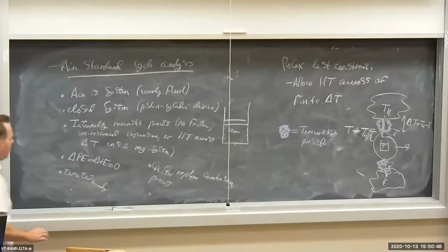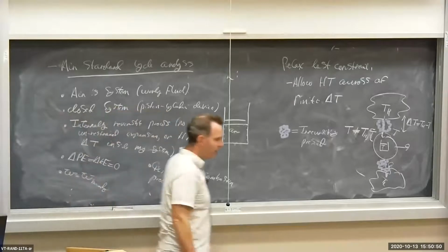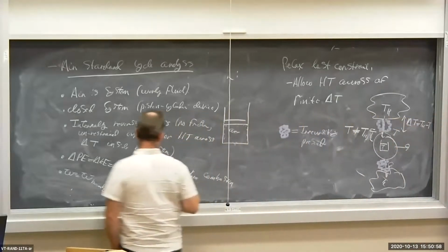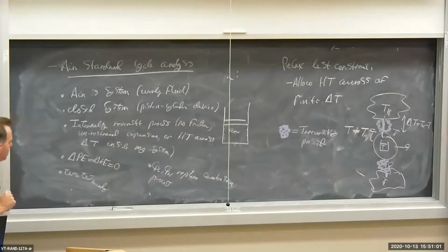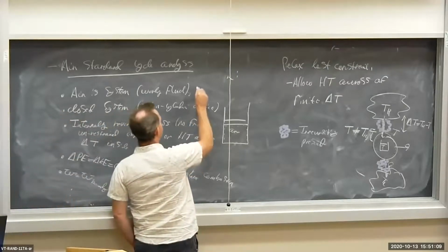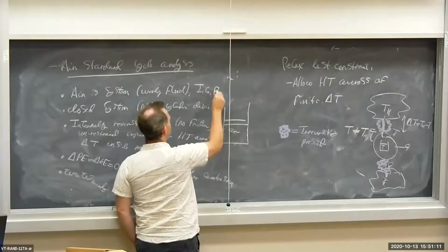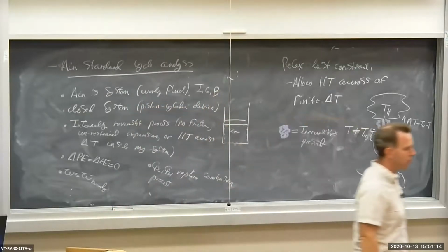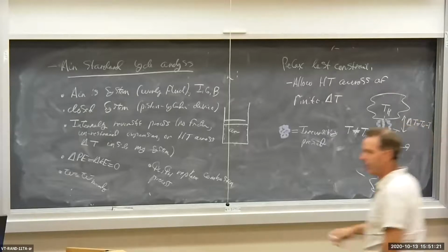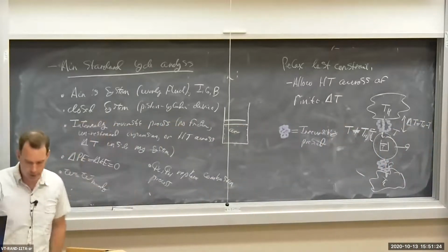So we're replacing the combustion process and the replacement of burnt air-fuel mixture with simple heat transfers, QL and QH. Okay? And also, I didn't put it down here, but I'm going to write right here ideal gas behavior, IGB, ideal gas behavior, we're going to assume for the working fluid. Okay? All right, let's take a break for a second here. Let's take a pause. We'll go on to some more material.